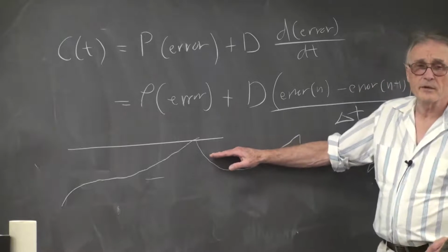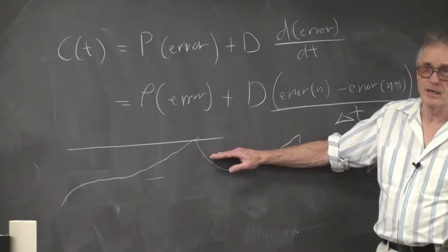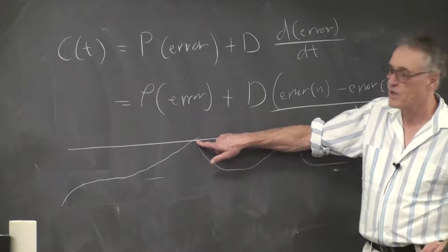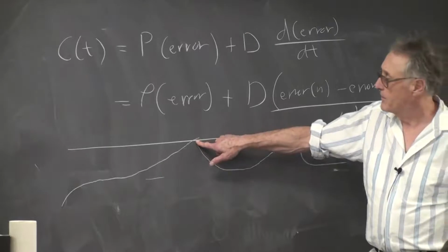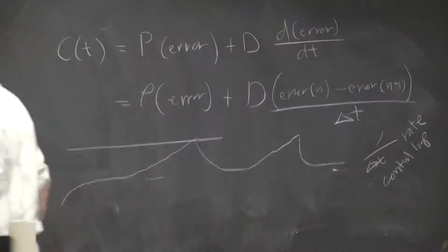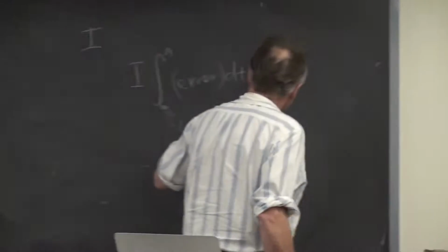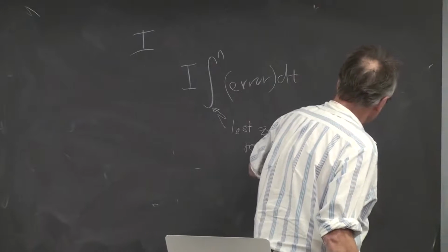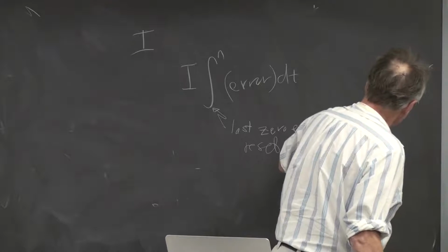What if we reset the integrator to 0.95 times its value when it crossed the value? So let's reset to 0.9 of the 0 crossing value.